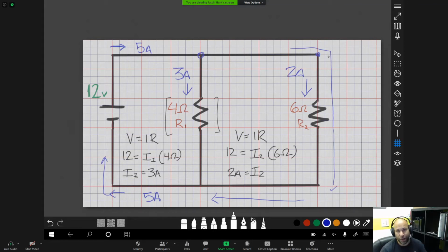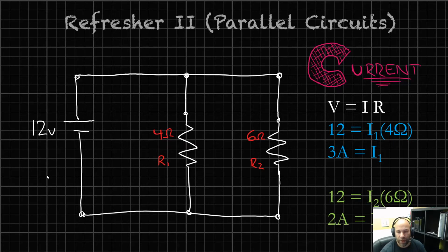It's also worth noting that for each one of the junctions that we're passing through, 3 amps and 2 amps equals the amount of amperage coming out. You're always going to have the same total amount of amperage leaving a junction as went into a junction. All right, and that's what we see here. We've got our 5 amps coming out of the battery, shedding 3, 2 carry on, coming back around the bend, rejoined by our 3 amps, 5 amps going back in the battery.